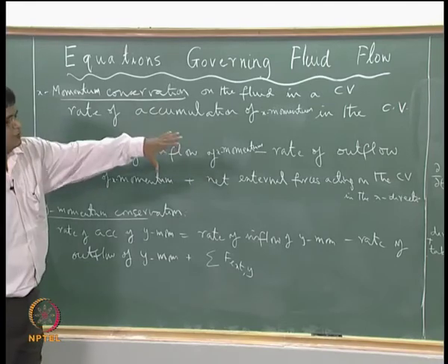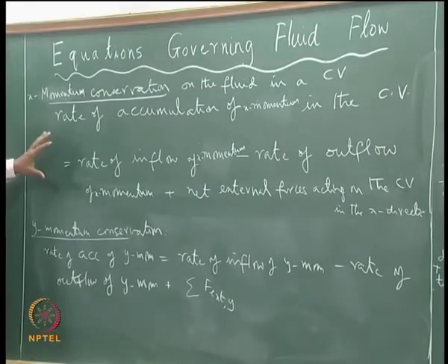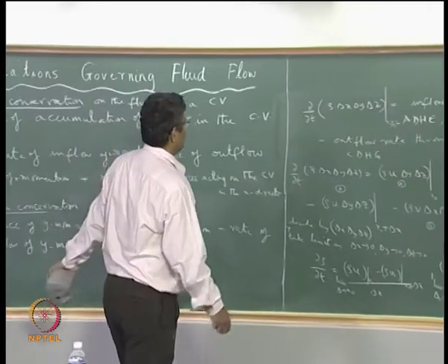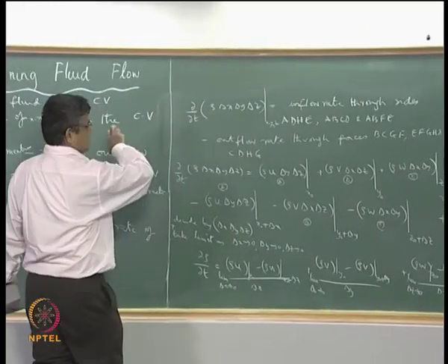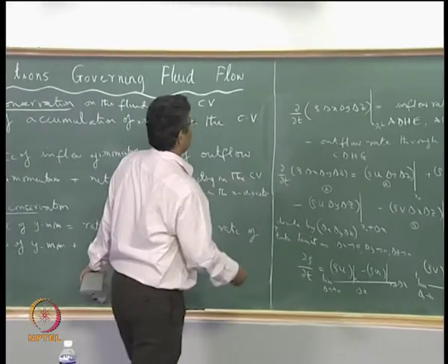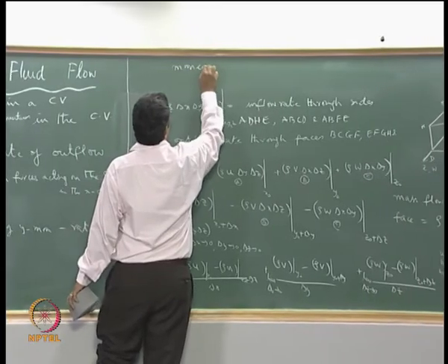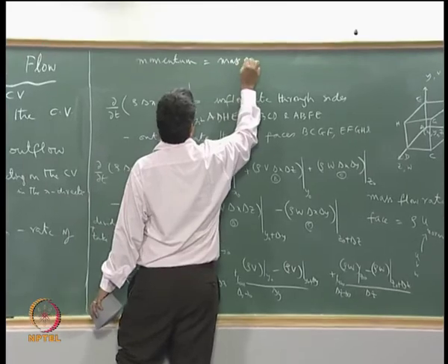So, using the same procedure as what we have adopted for the mass conservation, we can convert this verbal statement into a mathematical expression by essentially following the same way. Rate of the total x momentum, we know that momentum is mass times velocity.